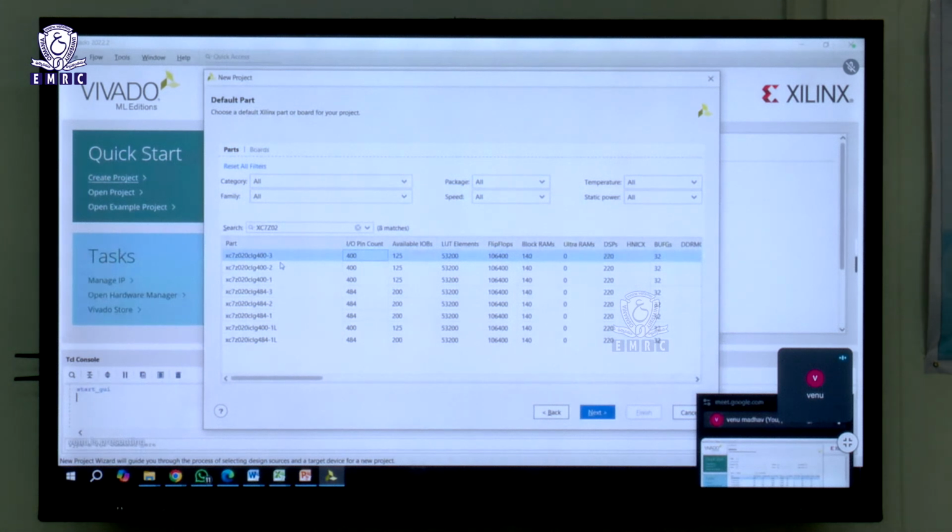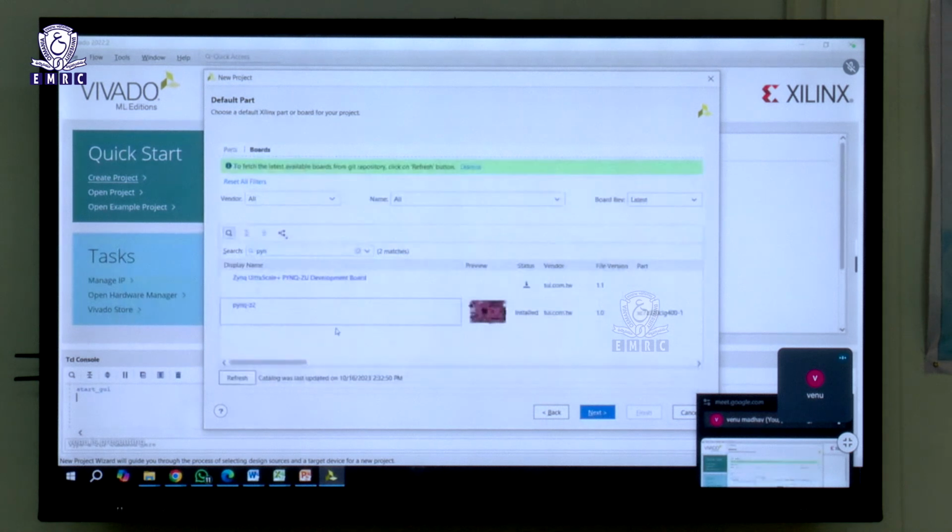But if I have a board support package, BSP, this is already mentioned there. It says that these are the pins that are connected to this peripheral. It can be anything, not just HDMI. It can be buttons, switches, the Ethernet port, the power supply, everything. That is directly available. So how do I access the board support package? How do I add this particular PYNQ-Z2 onto my tool?